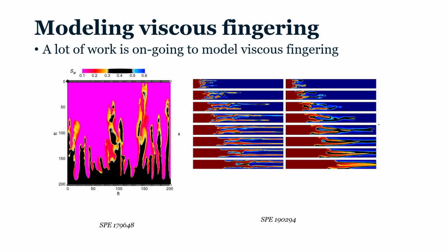It might give you very optimistic but wrong results, saying that the polymer has damaged the rock, there will be no fingering in the high-perm zones, water will be diverted, and you will get 1% extra oil just during the water chase. Once again, so far, field evidence has not corroborated that.